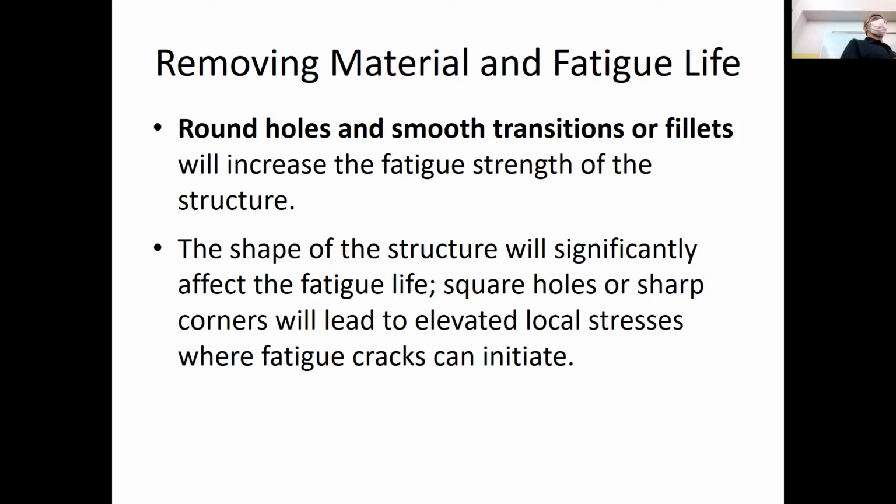Loading, unloading, you have a minor crack, it keeps propagating until it leads to failure. And this is why sometimes smoothing a surface or removing material could enhance the strength of a part that is loaded in fatigue. So keep that in mind, which is usually not typical. Usually you think, oh, I add material, I make it stronger, right?